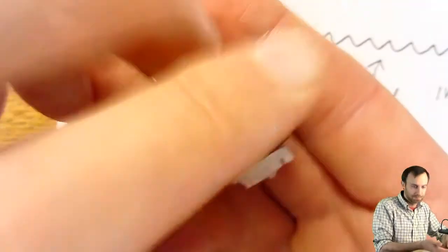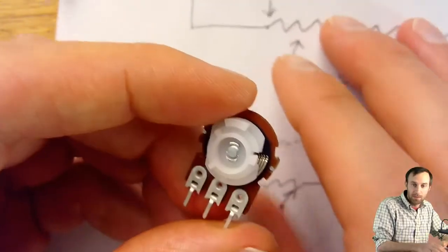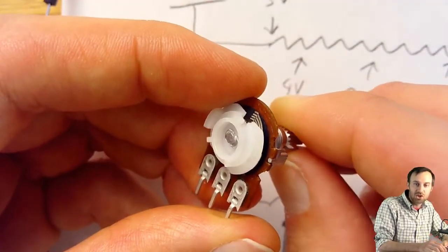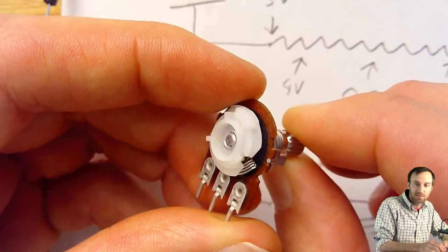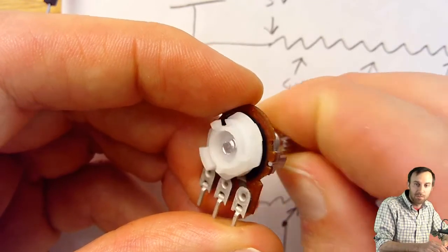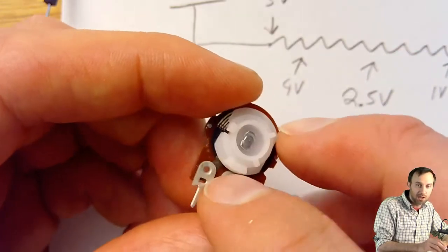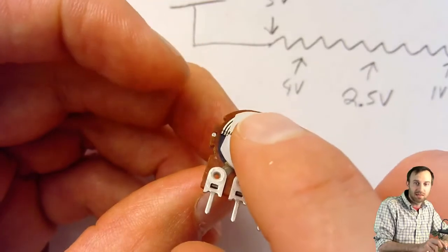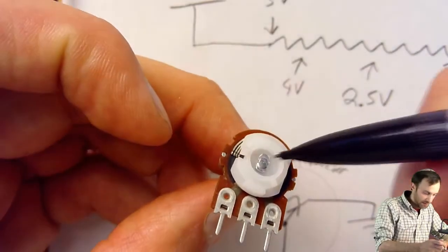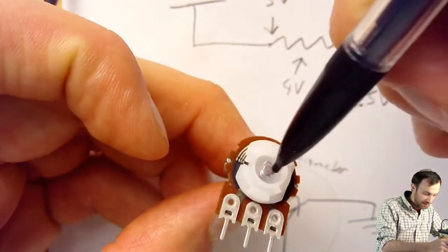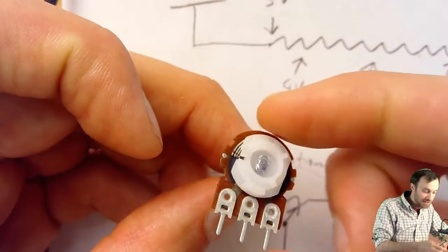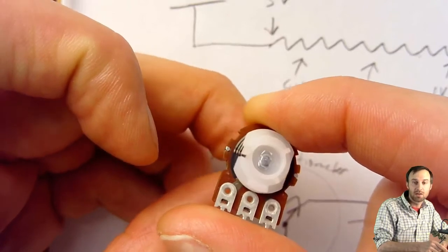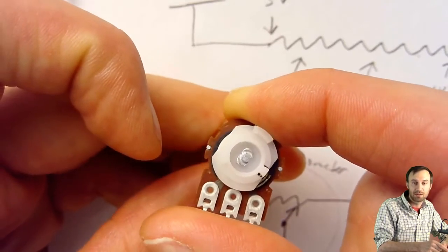The middle is the wiper, and the middle are those little metal things, and look at that, they change where they touch it physically. As I turn the knob, they change where they touch it. And where does that middle leg go? It goes down to this middle leg. So this thing is connected to this thing, which means you can move the place the middle leg is touching the resistor, which travels along the outside of this.